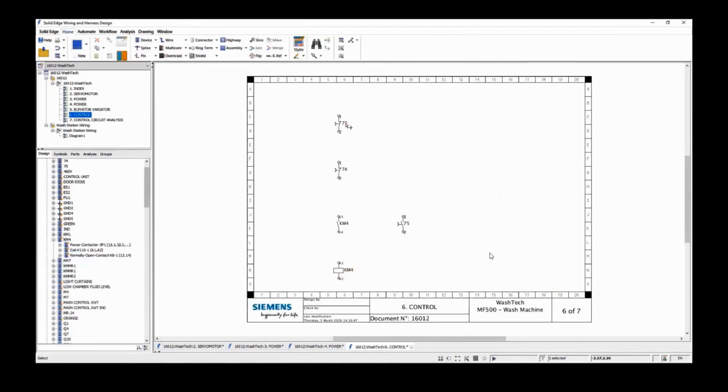Now we can rename the components if required. If we add the same name as one already in the project, then the DRCs, the design rule checks, come into action, indicating in red that it is already in use and cannot be used.